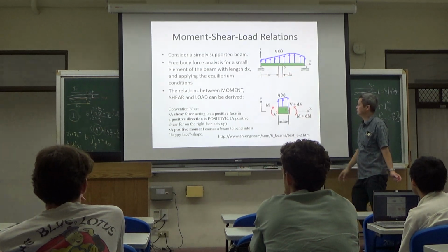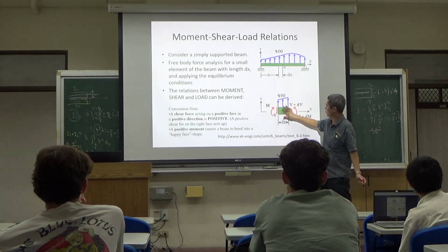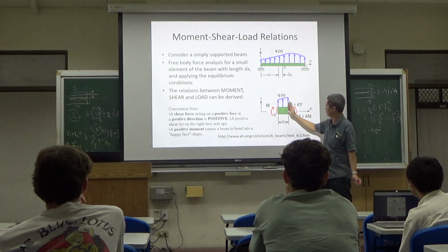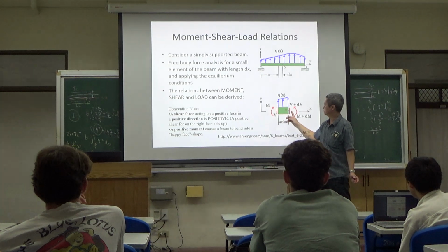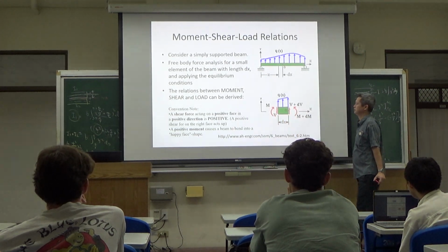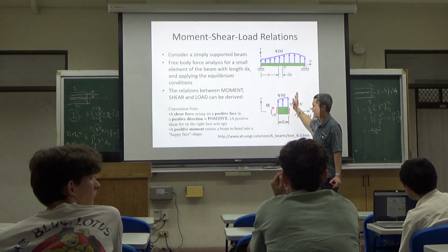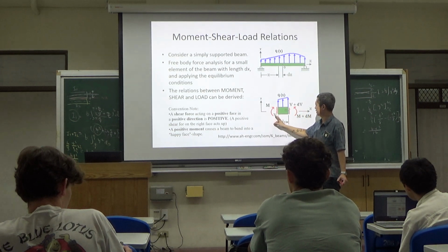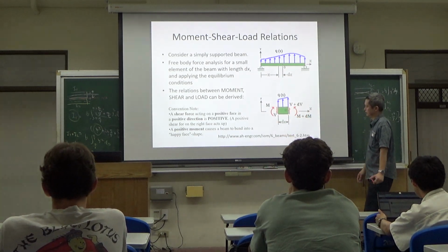As a result of the distributed loading, if you do the integration of the load along the length, it must equal a certain force. This force must be overcome by the shear force on the cut at the two ends. If you take the cut on the right end, you have upward shear force positive, then you have negative or downward shear force on the other end.